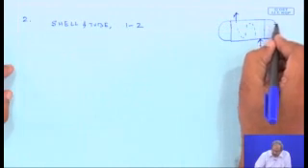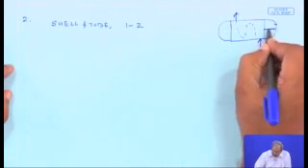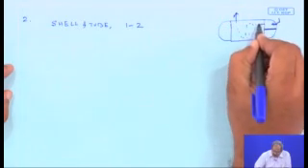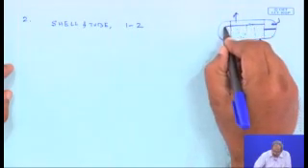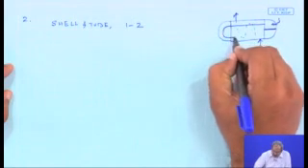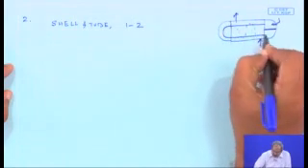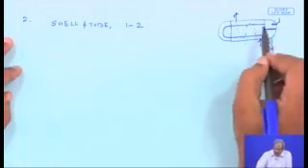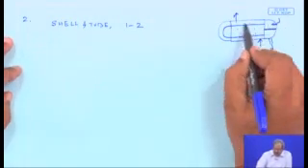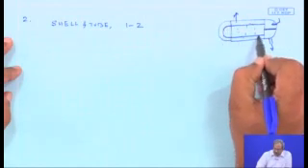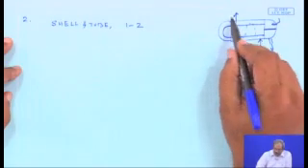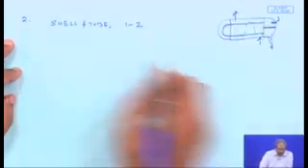But on the tube side there is a divider over here. So the fluid enters through this, passes through the tubes, changes its direction, travels back and is collected from here. So this is a 1-2 heat exchanger, where the tube side liquid passes through the shell twice, whereas the shell side fluid passes only once.